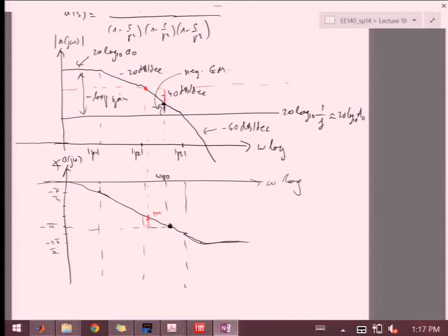But once we analyze it and we figure out we're in trouble, we have to do something about it. Right? And so in this previous case, let's say we're in trouble because the gain margin was negative, or even if you look at where your unity gain is, you're roughly at pi over 4 phase margin, right? So that's a problem. Okay.